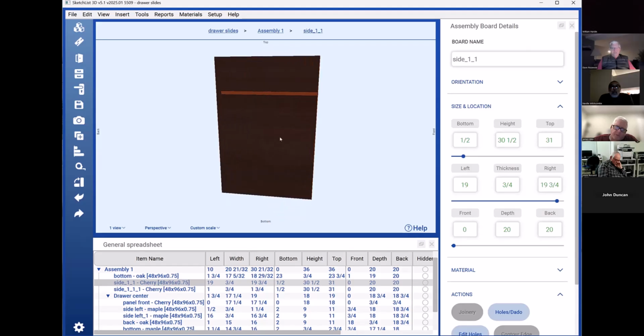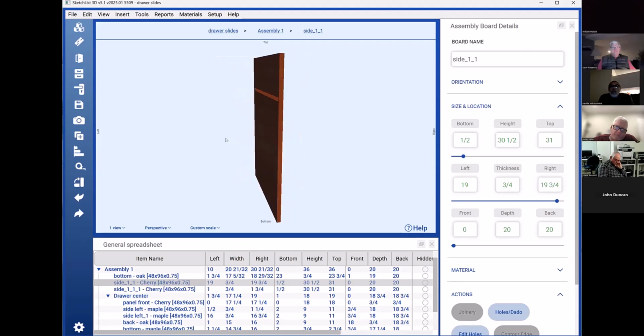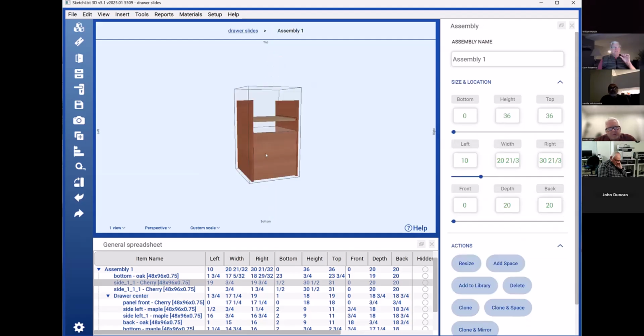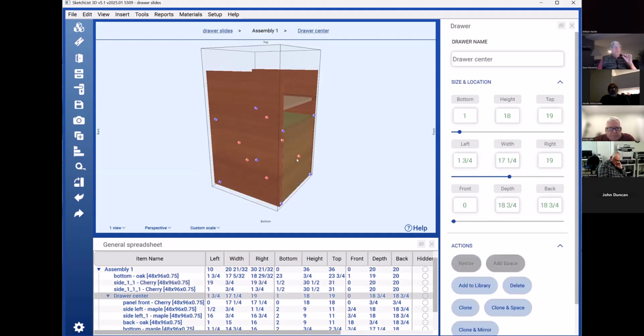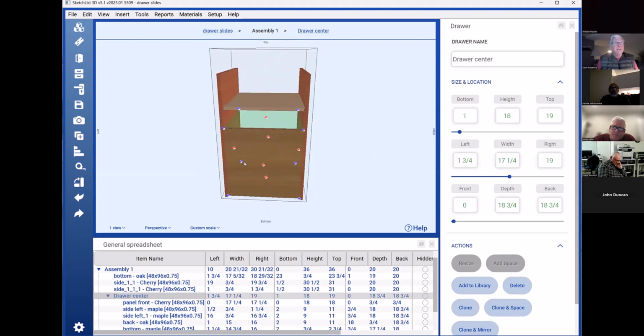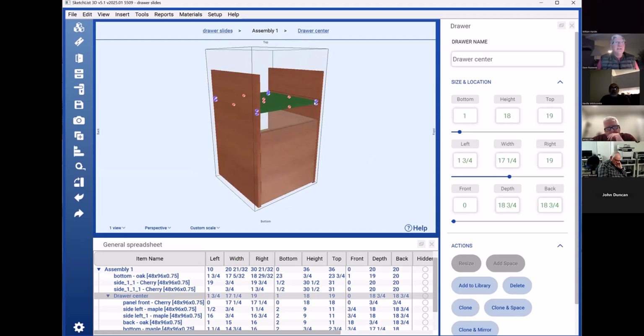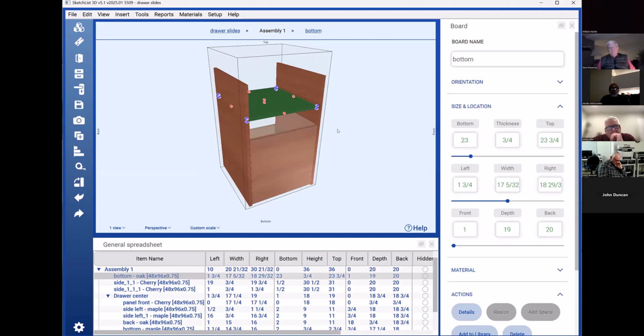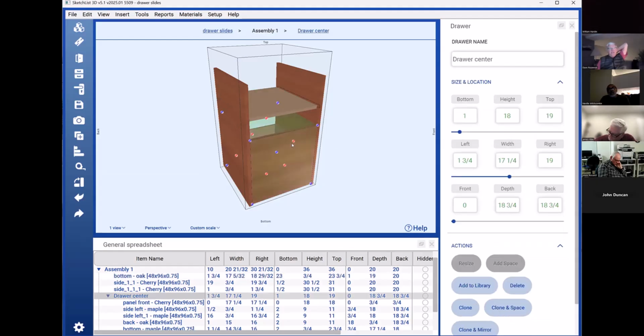If you bring the shelf level to the face of the board. Yes. The tenon, you mean? Well, the tenon is going to have a haunch because it can't come all the way to the front unless you're bringing it set back from the face of the board. Yeah, there it is. Yeah. So what you do is you just make the dado less wide. You could do it front and back. You could say give it an inch on the front, an inch on the back, and it would have, yep, 18-inch width on that. All right.